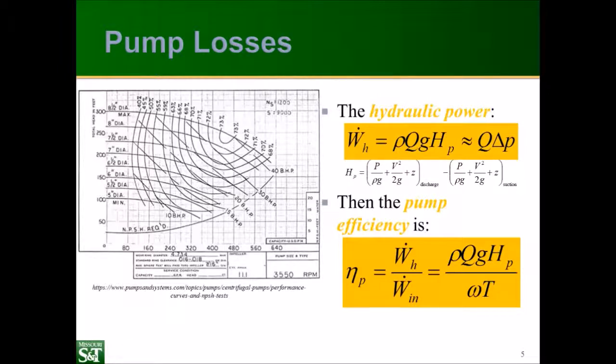And you can see our typical head flow rate curve here for the 8.5-inch diameter, head in feet, and flow rate in GPM. And this is a curve that's very similar to the one for our backward curved blades that we just saw. Now, these lines show that bigger rotors produce more head for the same flow rate, which makes sense because since the radius is bigger, the runner speed at the exit will also be more.